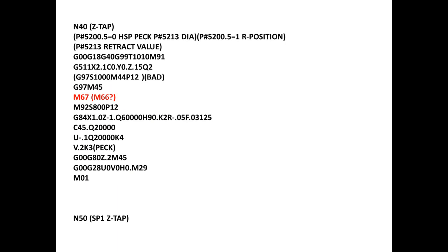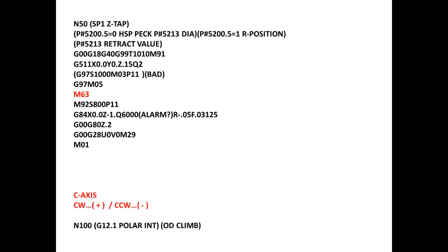Since we're talking about the tapping cycle, I wanted to cover the spindle tapping cycle. This one is not a live tool. This is a solid, stick tool tapping cycle. Same parameters, still controlling the spindle tapping cycle. Whether you want to do peck tapping or straight tapping, we'll do exactly the same.